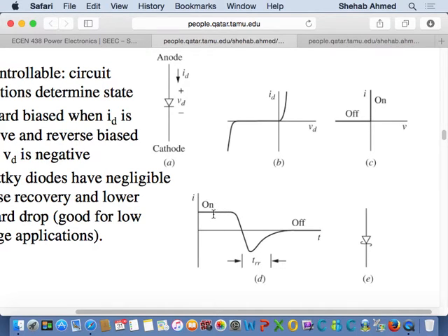If you're considering that you will switch off and then back on here, can you do that? I cannot. I cannot switch off here and then back on here, because there's reverse recovery time. The diode is still not blocking, right? So it will limit switching frequency. It will increase losses in both the diode and the MOSFET because it's flowing through both, and require some additional filtering requirements. So all of these things, right?